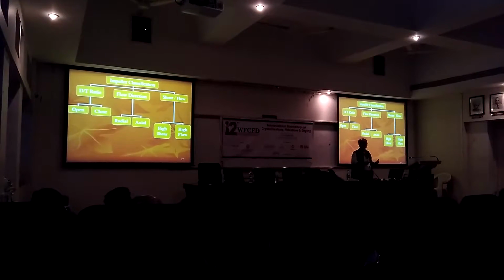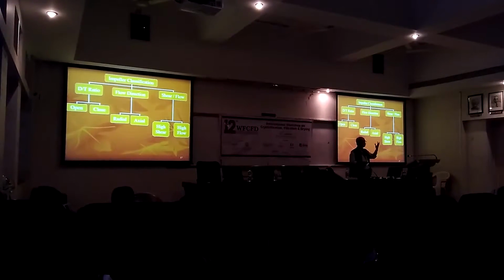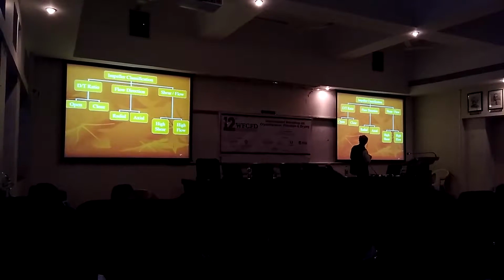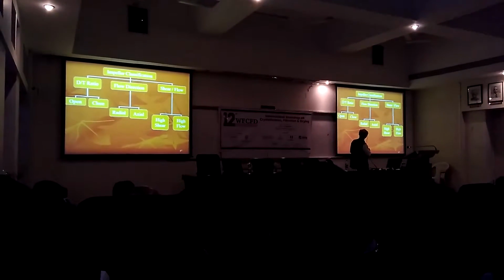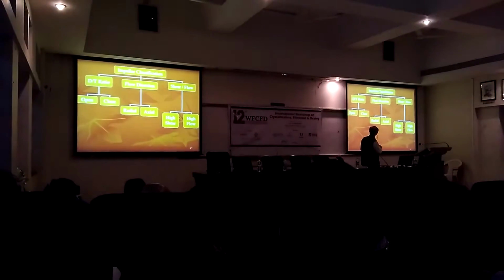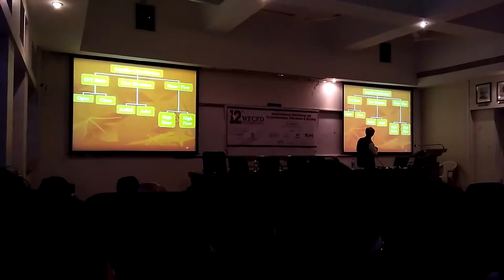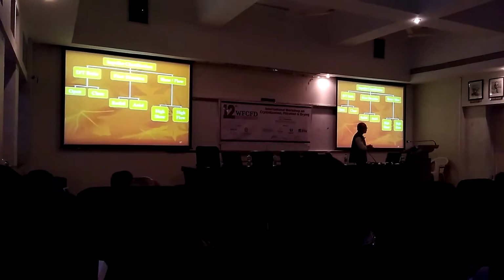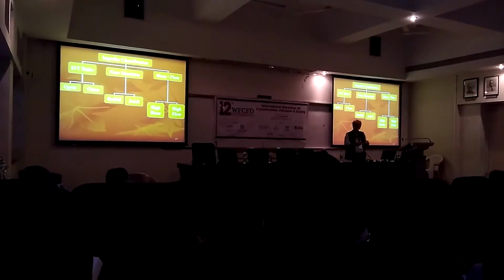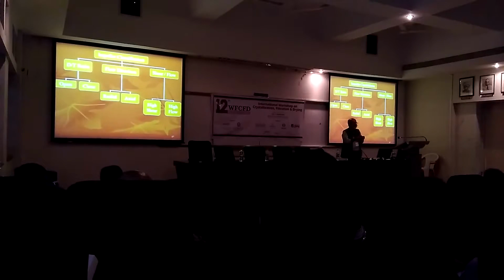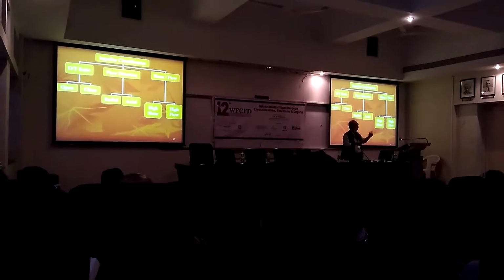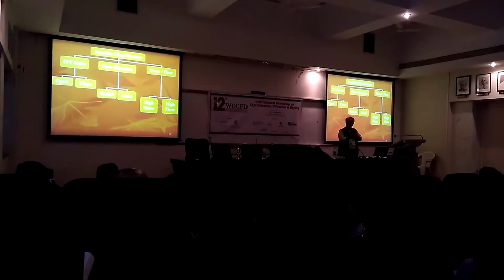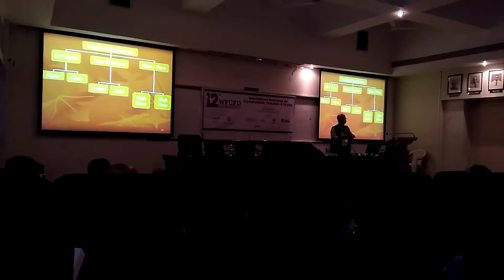To be able to achieve this, which is suspension and heat transfer, you have to use some impeller, some agitator. And what choices do you have? You have choices in terms of diameter of the impeller to tank diameter, vessel diameter ratio, the direction of the flow which is created due to the impeller action, the kind of shear, if you want to de-agglomerate the crystals, if crystals have a tendency to agglomerate and form larger crystals, not because of growth, but only because of agglomeration, then you need to create a fluid shear so that this de-agglomeration takes place and you get the original crystal